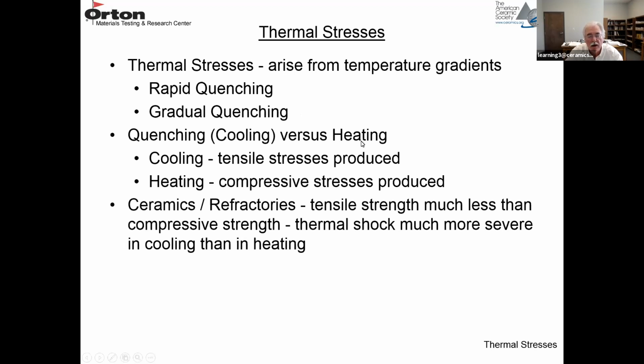You can also have rapid heating, but what happens during cooling is the outer surface of the refractory is basically contracting while the inner surface is not. So you develop tensile stresses on the surface. Heating, the opposite happens. The surface is expanding faster than the interior, so you develop compressive stresses.